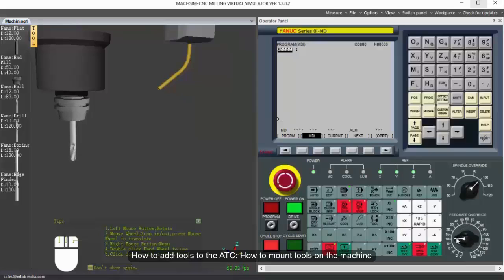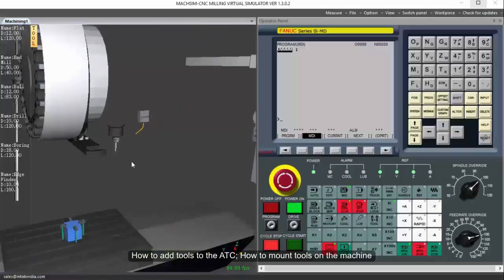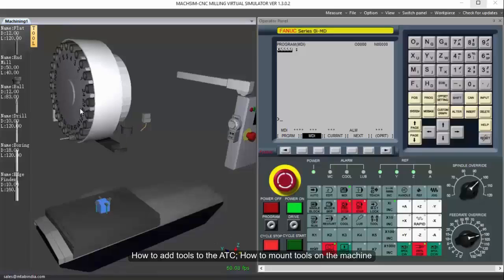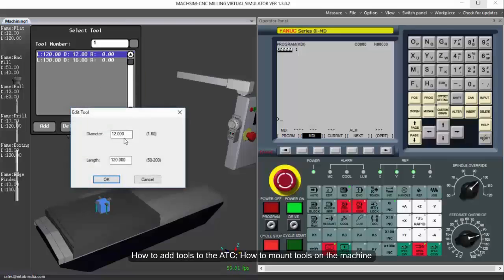Just as in the real machine, the user can use the MDI panel to call tool change operation. The user calls the M06 tool change code and enters the tool number desired and executes the command using cycle start. When calling tool 4 for the operation, the user is adding an electronic edge finder for taking offsets, which will be demonstrated next.